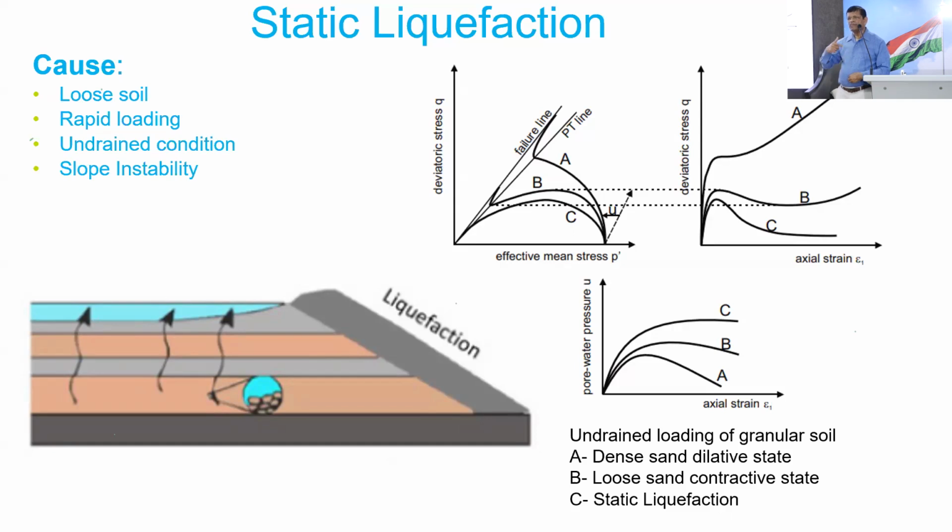So when I was analyzing the data, mostly coming from the CPT, we saw that we took some repeating tests of the CPT. With time, the data we got 15 days after the failure, I saw that the pore pressure is declining after the failure.